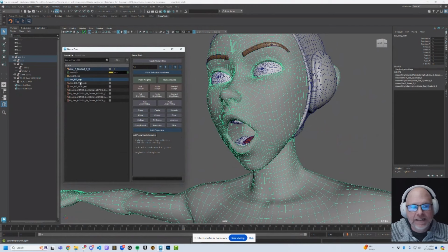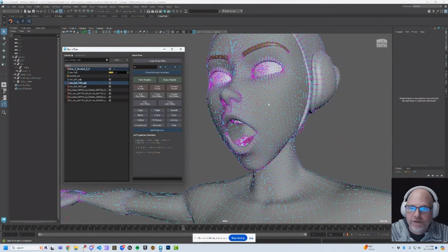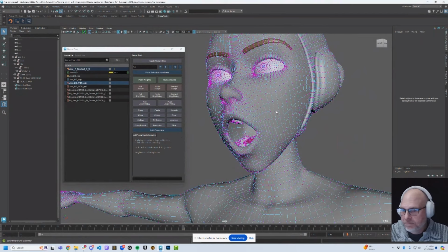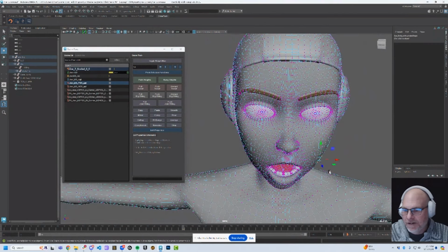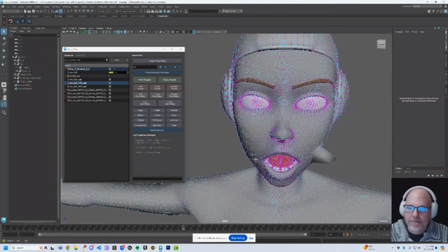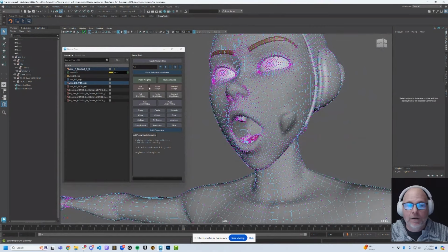Here I'm going to do UD, so we're only looking at the up and down. So let's add a sculpt in, right? I'm going to come in here, and what we do is I'm going to pull a sculpt. It takes wherever the state of the character is and makes a copy that you can do any kind of modeling with. So I go here and I pull sculpt. It's now created a separate model that I can model with. So I'm going to do something simple. Let's pull some points out here, right? So now I will push that in, and I'll say, hey, push it in there.